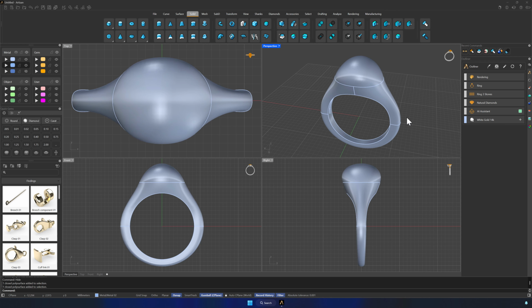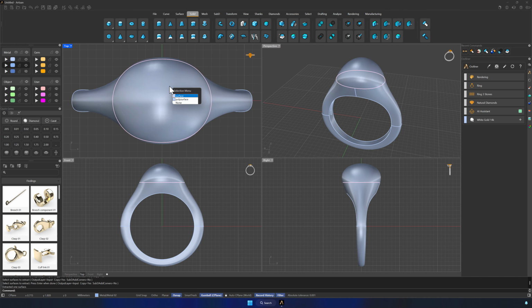To do this, the first thing we will do is extract the top surface. Make sure that in the command bar the copy option is set to Yes. Also, show the curves. We will only need the one crossing the surface. The rest can be hidden.